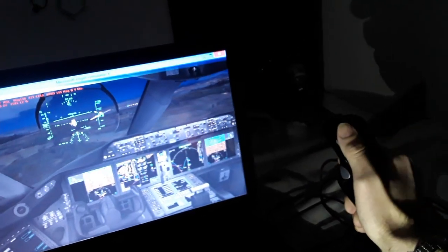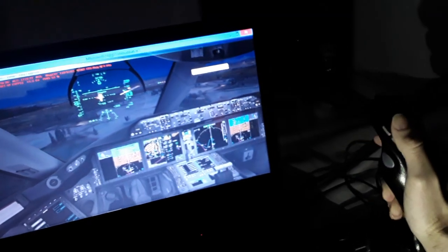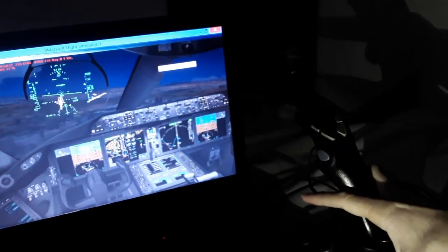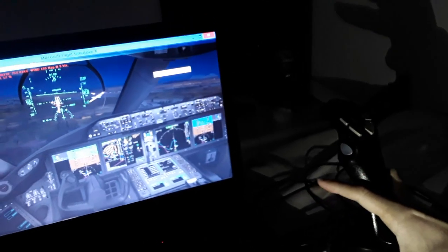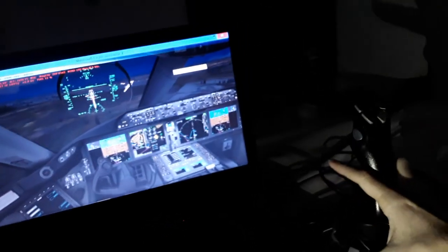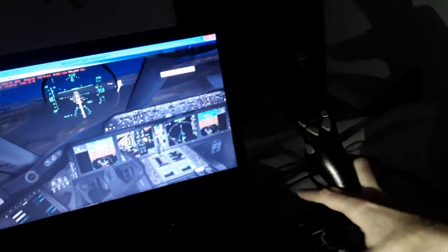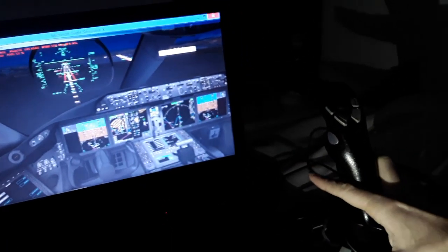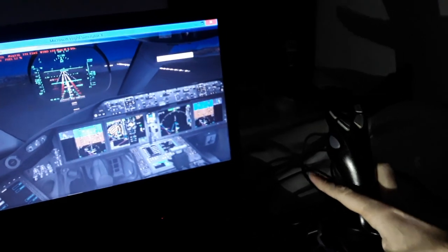This makes the alignment more difficult. We need to use the rudder pedals also as we are approaching for landing. We need to combat the side wind. We need to maneuver to line up with the center line. Use a little bit more or less thrust from time to time also. Manual thrust and manual flight controls.